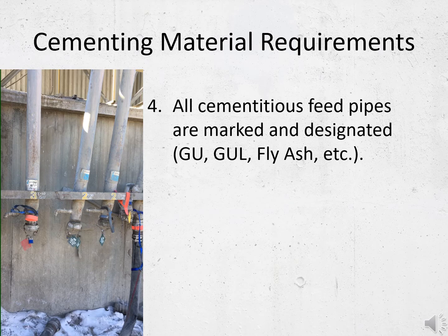If silica fume is used by the facility under audit in combination with fly ash and cement to produce concrete for C-1, C-XL, A-1, and A-XL exposure classes, rapid chloride permeability reports representative of the concrete produced with any or all combinations of cementing materials used by the facility should be on file and readily accessible.